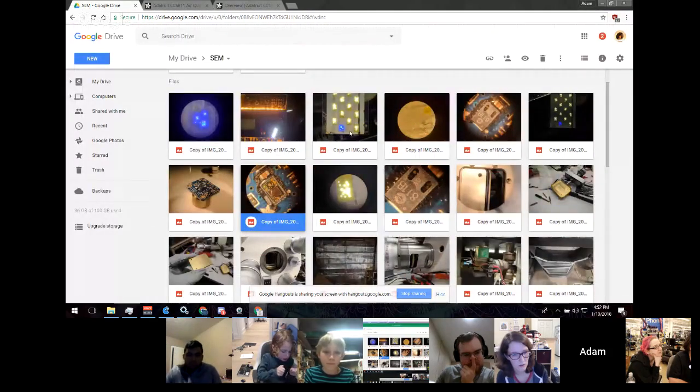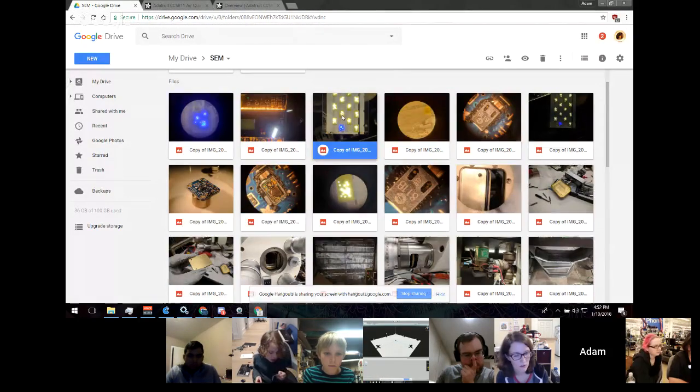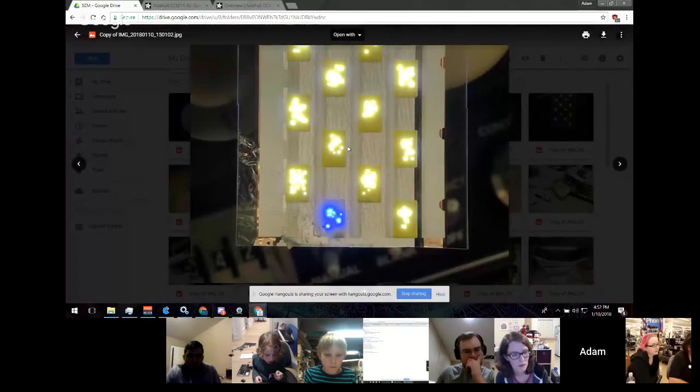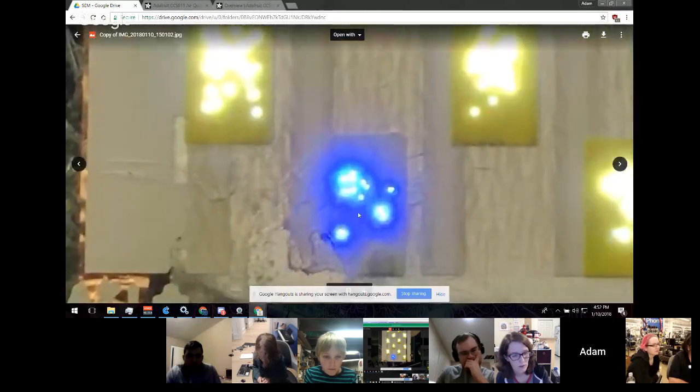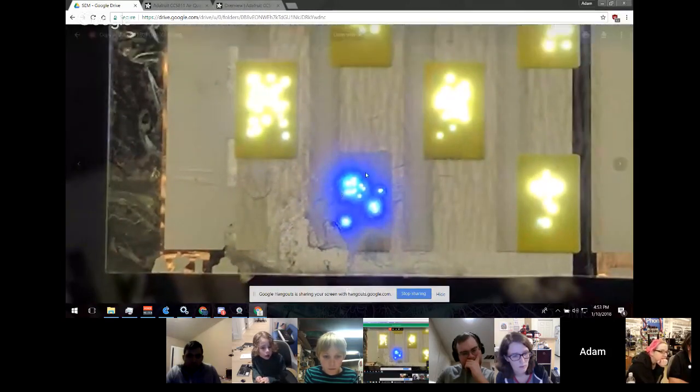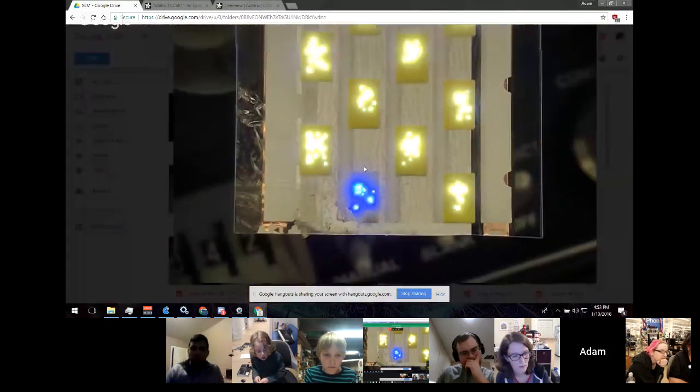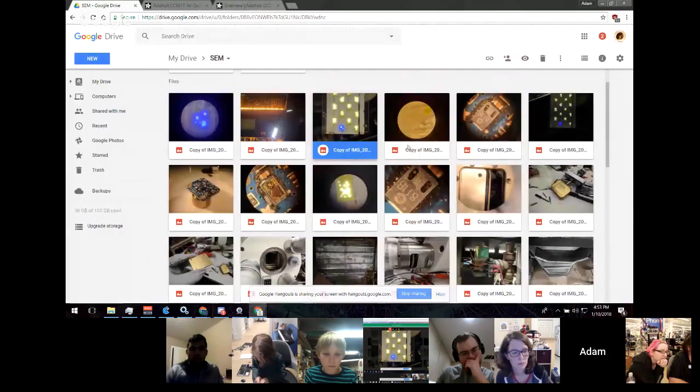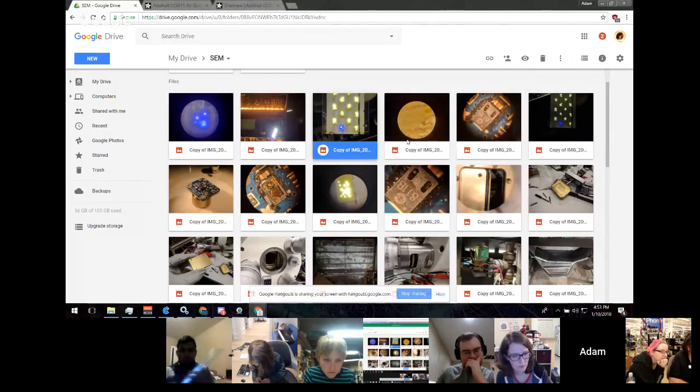I got the Flex 9 LEDs that you guys released recently. Is that right? Yep. Yeah, they're weird. I started taking them apart and figured out that the phosphor is on the top layer. So I'm actually able to scratch the phosphor off, and you're able to directly see it's just some blue LEDs underneath that phosphor coating. Oh, that makes sense. So right now I'm working on trying to figure out how to actually separate those two layers so I can get to the in between, the plastic and whatnot.